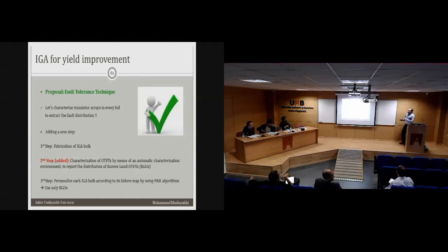Well, I think there's a trade-off between both of them, because the printing equipment is affecting a lot. In line configurable structure, we need to print very fine and long lines. This is causing some problems, although these problems are coming from the digital printer, but the structure is the reason for them, because it requires printing fine lines.